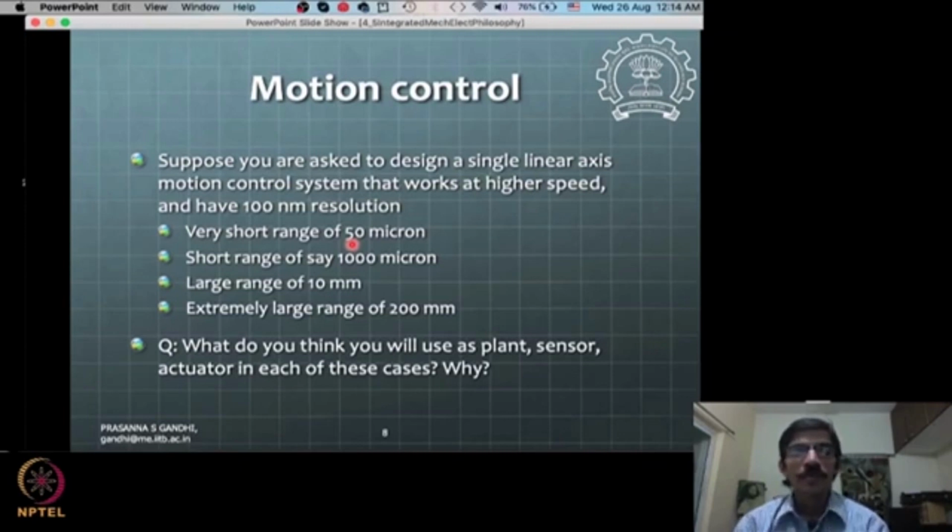Nowadays you'll also find there are something called inchworm motors. Let me see if I can give you some flavor of that; maybe we'll cover these inchworm motors when we talk about actuators. But basically, these are multiple piezo actuators working together in tandem, in the sense that they push something in the form of a wave.